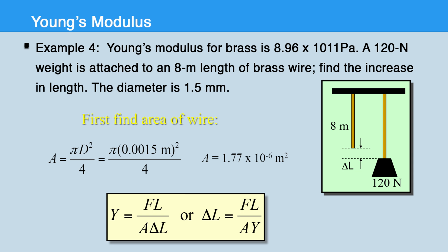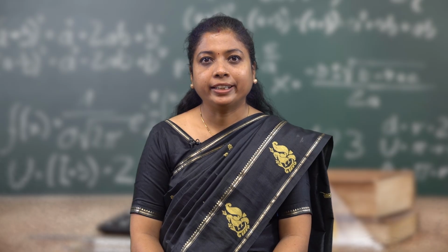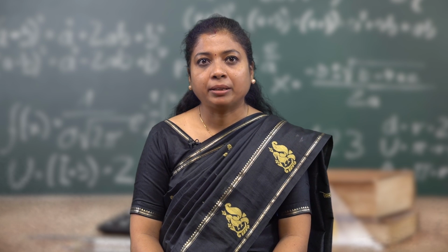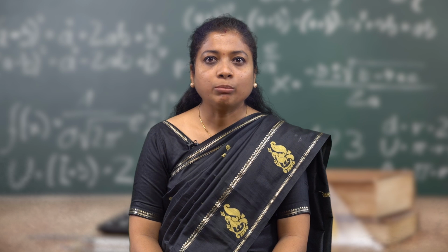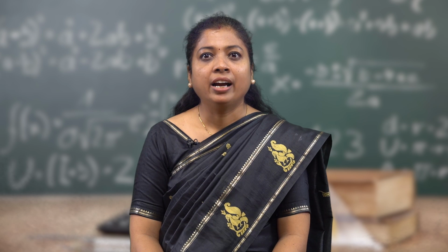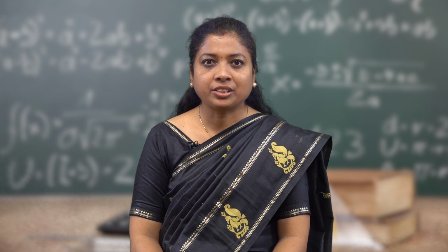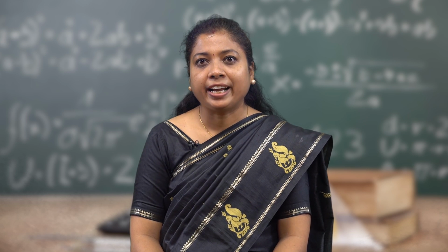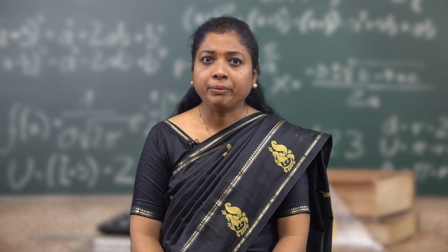Significance of the Young modulus. Stiffness indicator: a high Young modulus indicates that the material is stiffer, meaning that greater force is required to produce a small deformation. A lower Young modulus indicates a more flexible material. Design parameter: engineers use Young modulus to select materials for applications where specific stiffness is required. For example, structural beams in a building must have high Young modulus to prevent damage to the building.